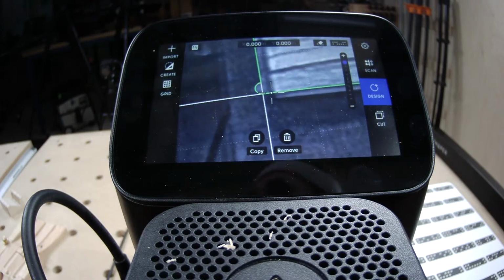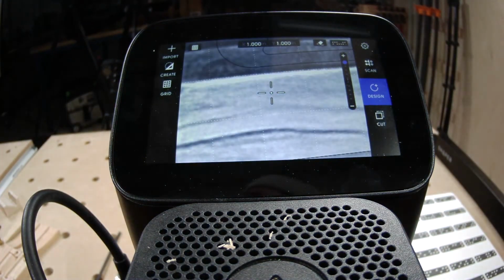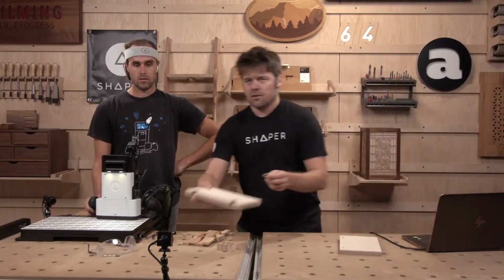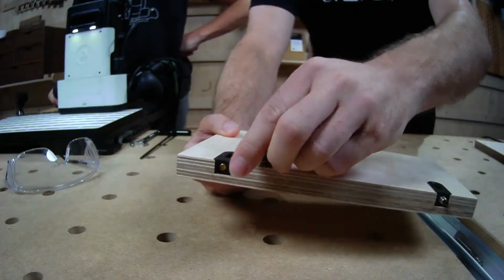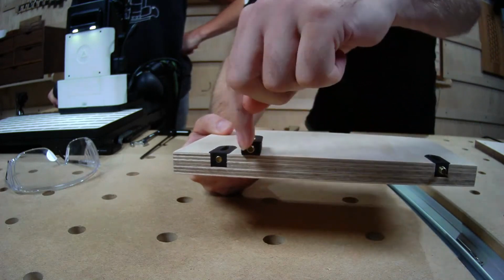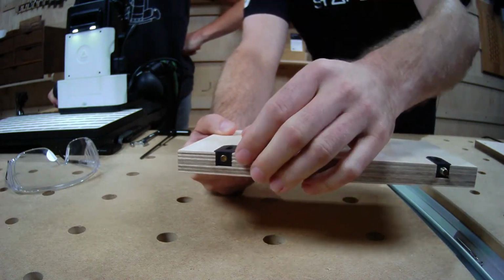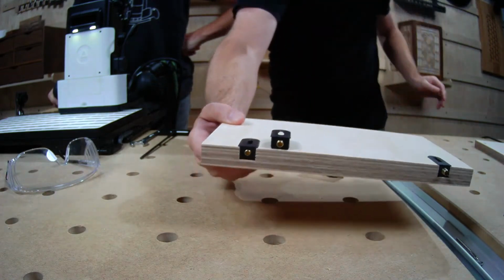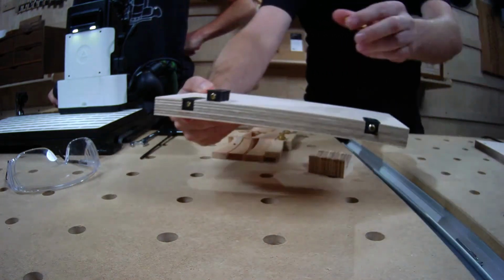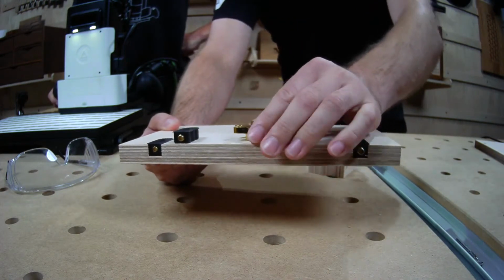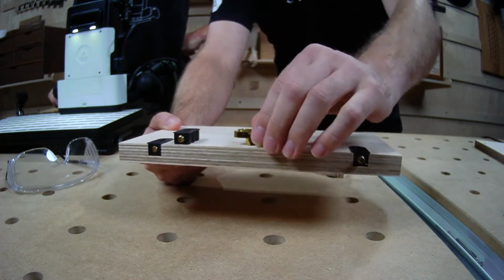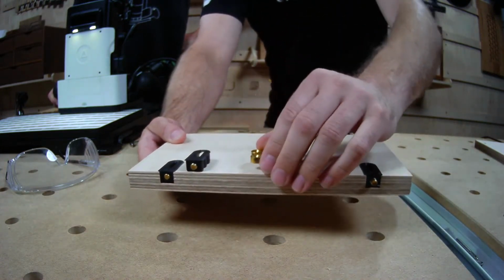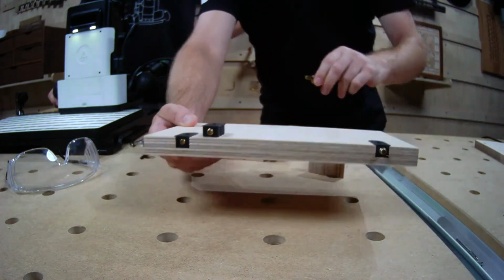So for things like those Cabineo files, these little guys, they are cut in a way that you cut beyond the edge of your stock. So that's where you want to offset these. And then the same applies to SOS type hinges. Like they might be 1/8 of an inch in from the edge. So you would just put your anchor point 1/8 of an inch below and you're good to go.